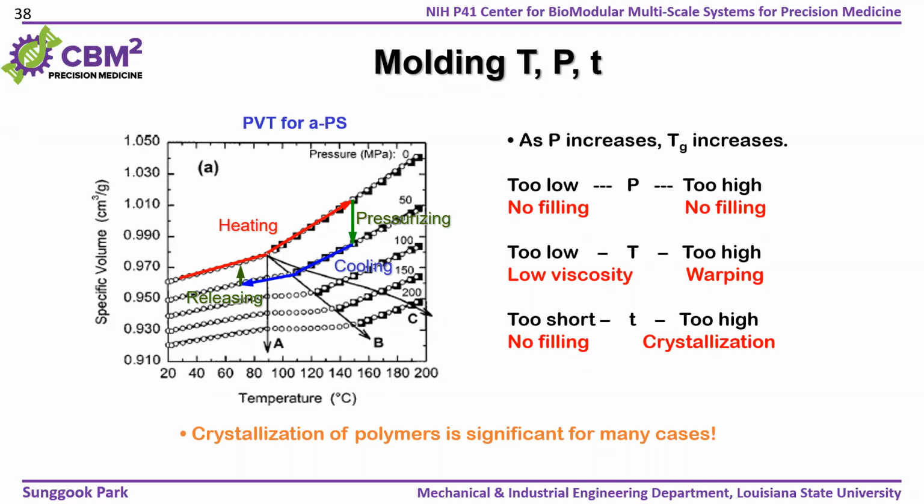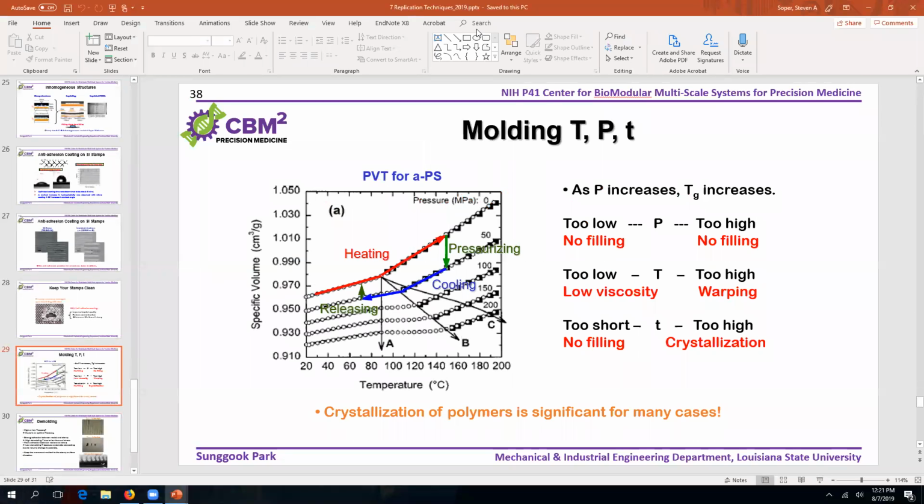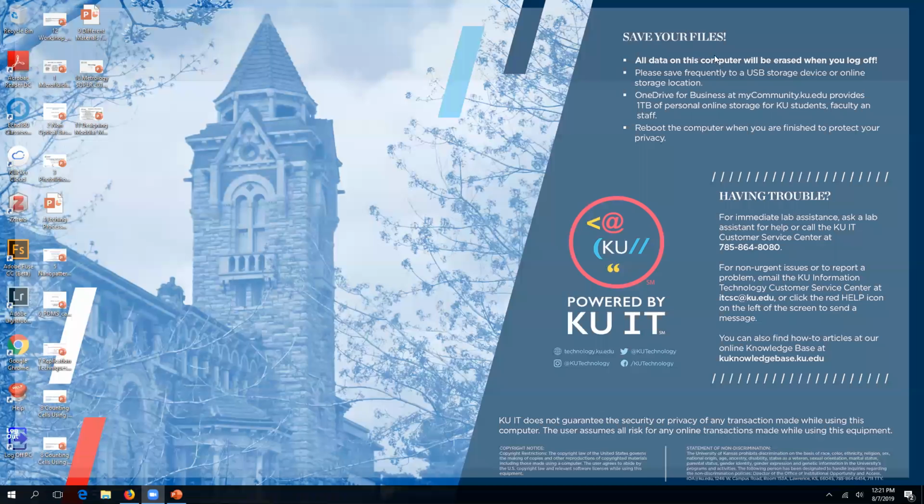I just want to add that parameters may be optimized, but they might also depend heavily on the substrate. And from vendor to vendor, thermoplastics may contain different amounts of plasticizers, for example. So it's not that the reported temperature, pressure, and time are not valid. They're valid for this